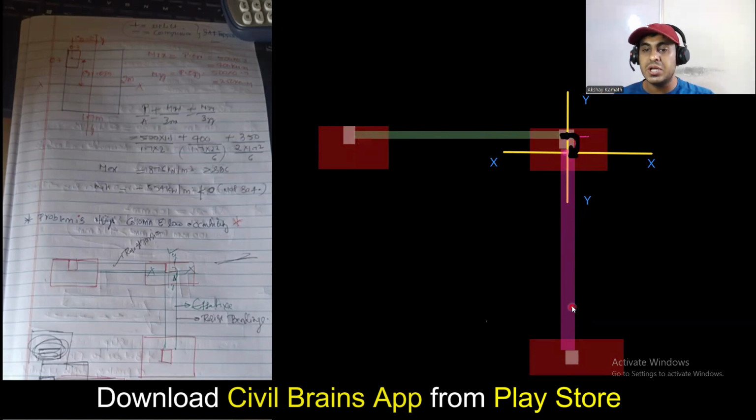But this particular beam will help you more in comparison to this one, because this particular beam is able to take the bending. So how will the bending be taken? You have to design your beam for that. Whatever moment is coming, you have to design your beam for that moment. Usually, whatever is the depth of the footing, that much will be the depth of your beam.